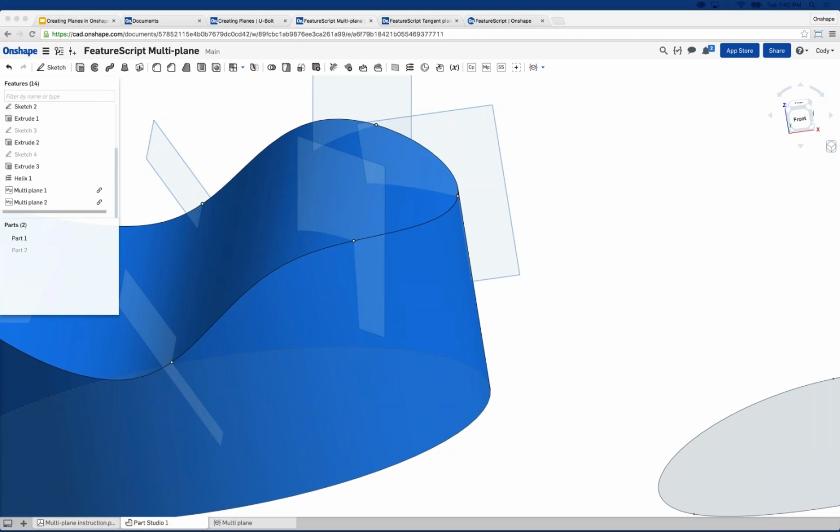Can you reposition one of the multiplanes along the spline? No. As of today, it takes the distance of the edge and evenly spaces it out, and then allows you to define how many planes you want along that given edge. Now, we could, of course, discuss workarounds where I split the edge into pieces, but this command doesn't have an option or setting to move one within the set. You could, of course, insert a whole bunch of them and insert one by itself. We could discuss workarounds, but this command doesn't have that, at least out of the box.